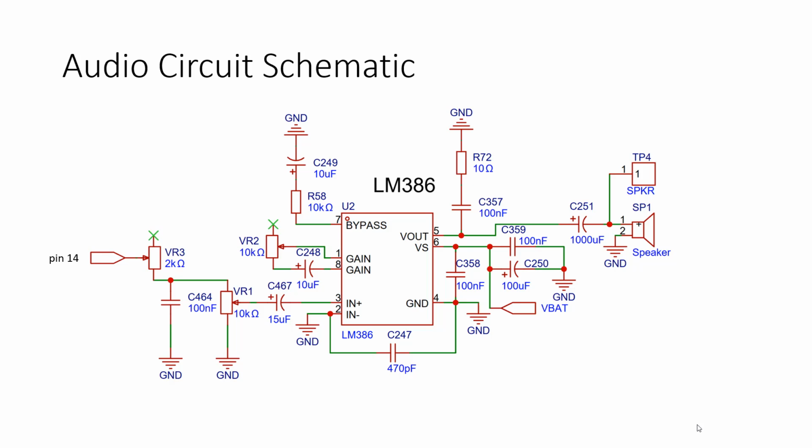But what's happening here is that we have this amplifier, the LM386 amplifier, that's used to amplify the signal, and at the same time we have some low-pass filtering going on in there too, because the pulse width modulated signal is like a square wave. And so if you send that directly into a speaker, you get some high-pitched, high frequencies in there, which you can eliminate with a resistor and a capacitor that are used for the low-pass filter, right?